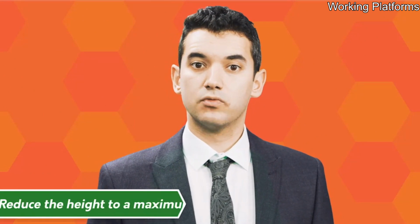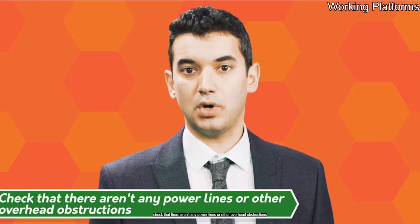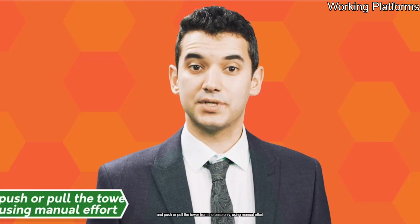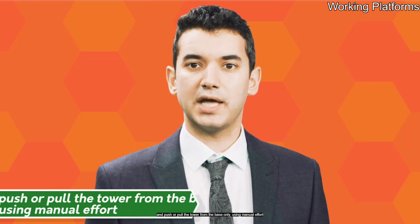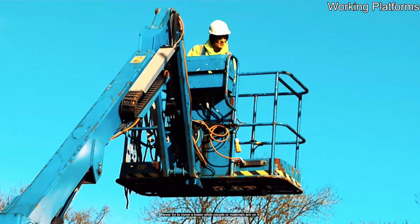When moving a tower, you should always reduce the height to a maximum of 4 meters. Check that there aren't any power lines or other overhead obstructions. Check that the ground is firm and level. And push or pull the tower from the base only, using manual effort. Never try to move a tower whilst people or materials are on it.